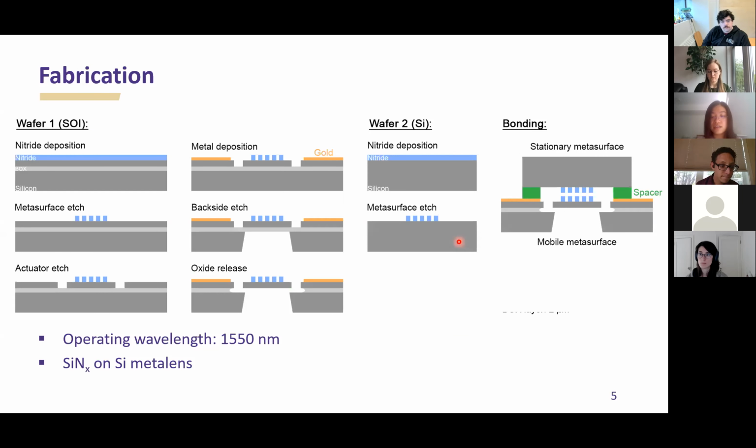And the devices in our project are all fabricated in the Washington Nanofabrication facility right on campus. For a full Alvarez system, the metasurfaces were fabricated on 2 separate wafers because there are 2 of the metasurfaces. Both of them are patterned with stepper lithography for very high throughput, high precision, but low cost. One metasurface is fabricated on the SOI wafer.